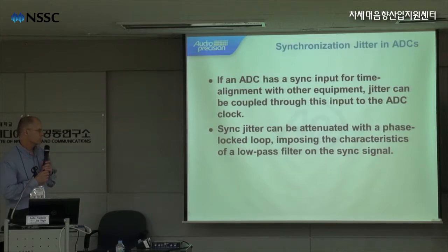Synchronization jitter can be attenuated with a phase lock loop, imposing the characteristics of a low-pass filter on the synchronization signal.